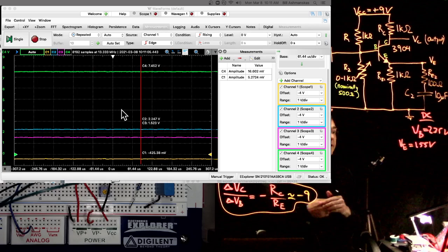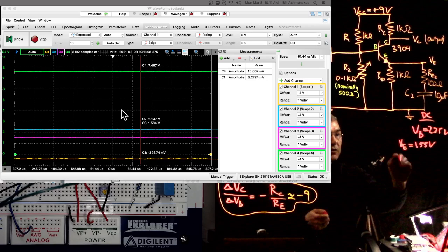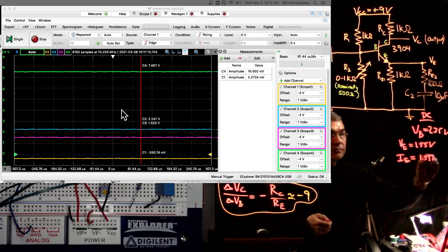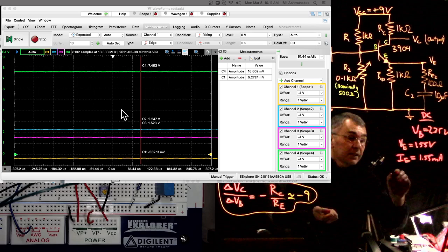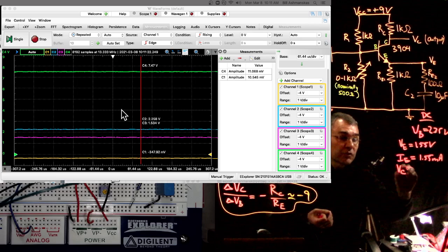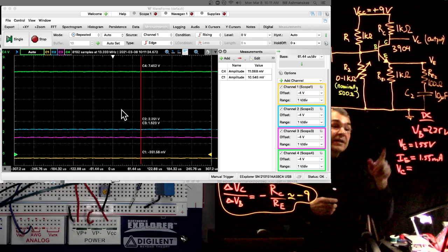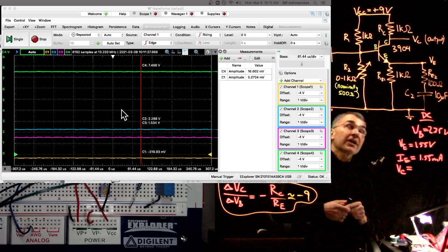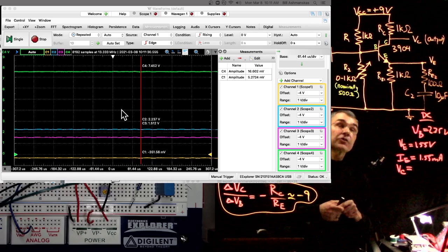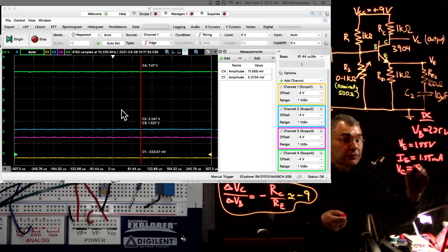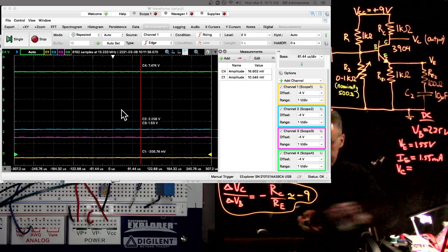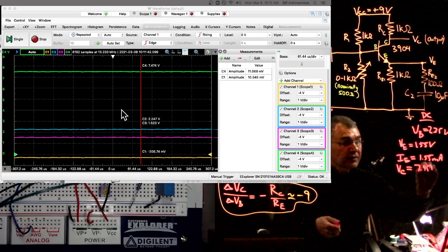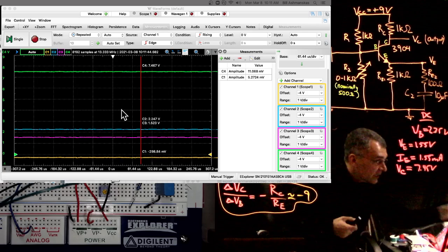That's pretty good. Okay. And then I guess we expect the emitter current to be 1.55 milliamps. And then the collector current should basically be the same. And then we expect the collector voltage to be 9 volts minus 1.55 volts, since it's VCC minus ICRC. So that should be, no, 7.45 volts. So let's see if we get 7.45 volts there. And yeah, look at that, 7.46.